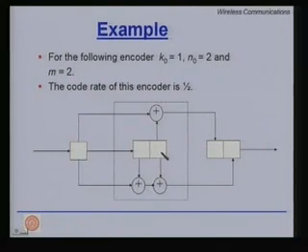And why is it coming like that? Because state is represented by what is sitting in the memory. This is your memory. If 0 0 was sitting here and this is a shift register, another 0 comes in, it will push here, this 0 will go here, and this 0 will be discarded. But for an observer, the 0 0 state transits back to 0 0. On the other hand, if I was sitting in 0 0 and a 1 comes in, then this 1 will go here, this 0 will go here, the last 0 will be discarded. So, the next state should be 1 0.